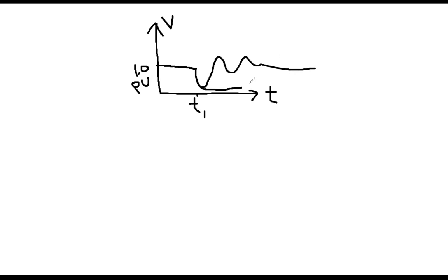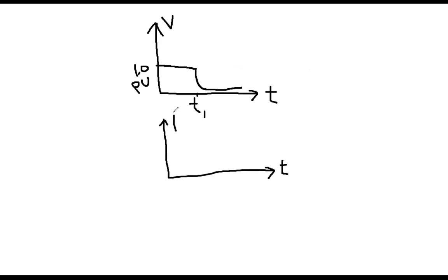unless you put some control means at the grid side, like some additional capacitor, some SVC, some reactive power compensator, STATCOM or other means. It does not come back. So that's why you will be getting this response ultimately. So that is your voltage profile. Similarly, you can draw the active power profile. So this will be your active power.